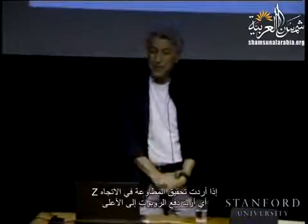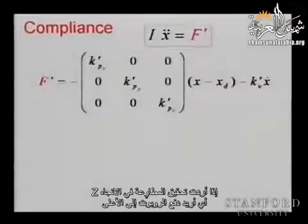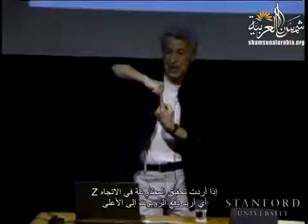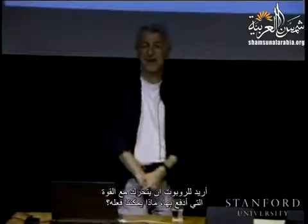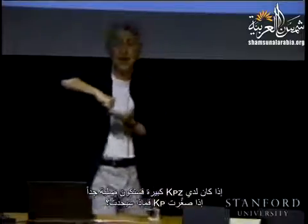Now, if I want to do compliance in the z direction, so I would like to push up the robot, and I want the robot to just move with the force I'm pushing with. What can we do? If I have a very large kp z, it's going to be very stiff.